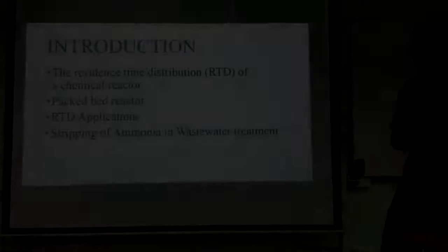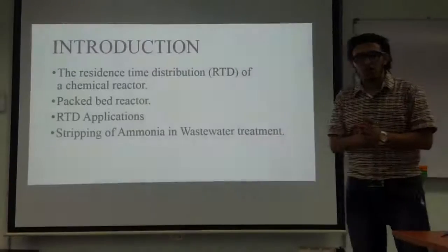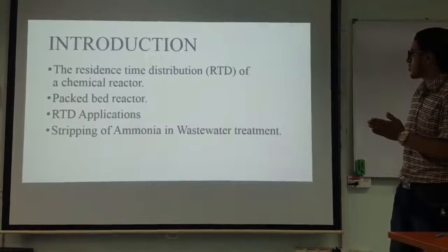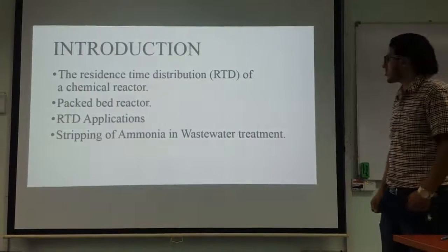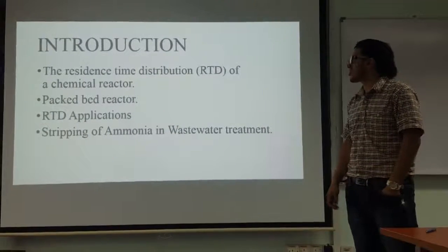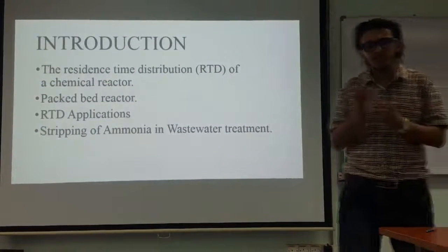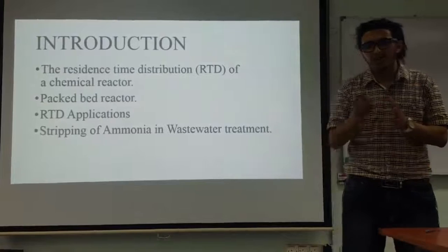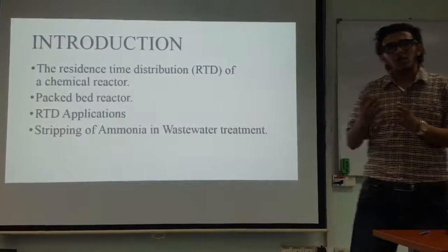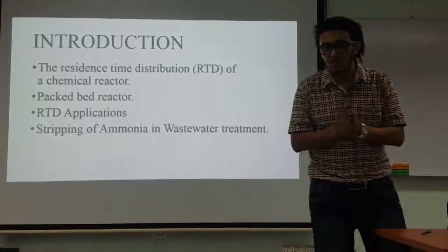In the first section, which is the introduction, I will give some explanation about the residence time distribution of a chemical reactor, packed bed reactor, RTD application, and the stripping of ammonia in wastewater treatment. The basic definition of RTD is the probability distribution function of the time a liquid spends inside the reactor.